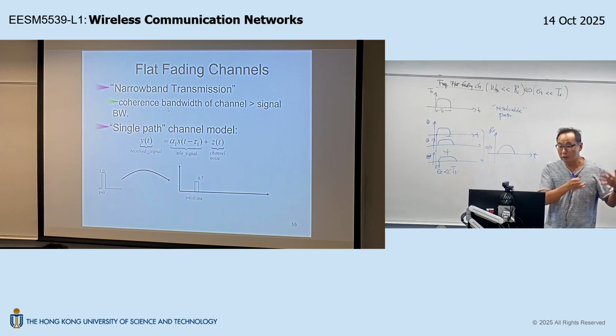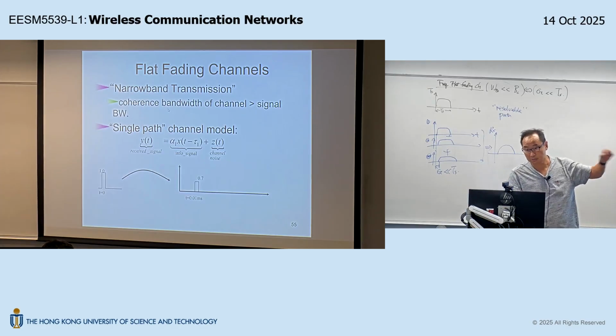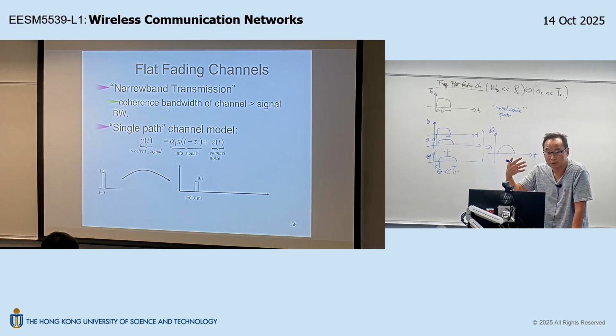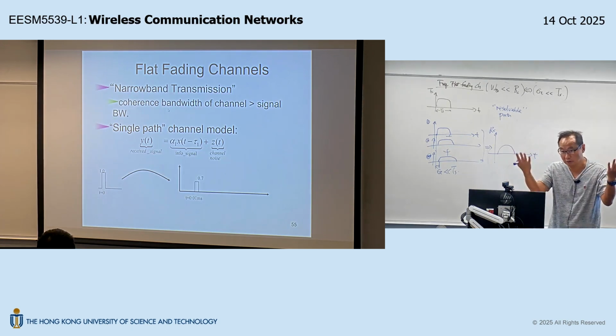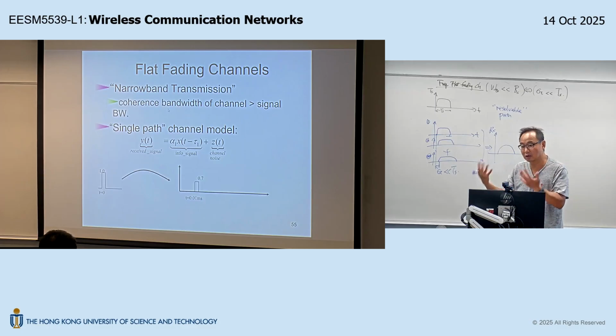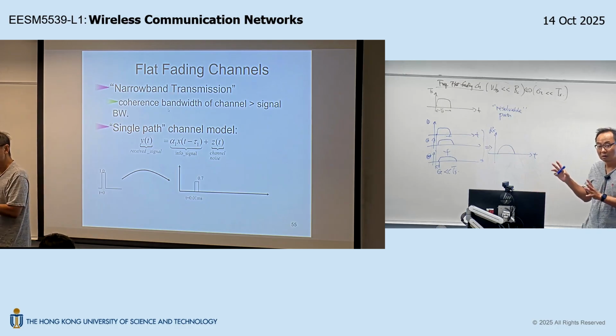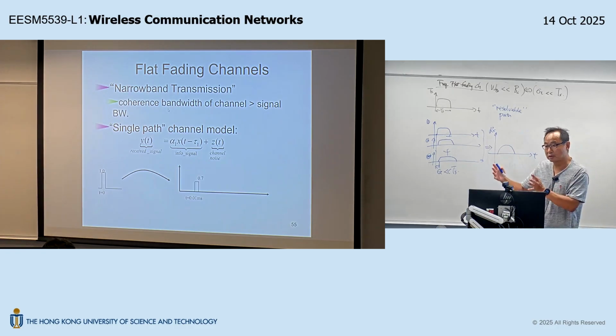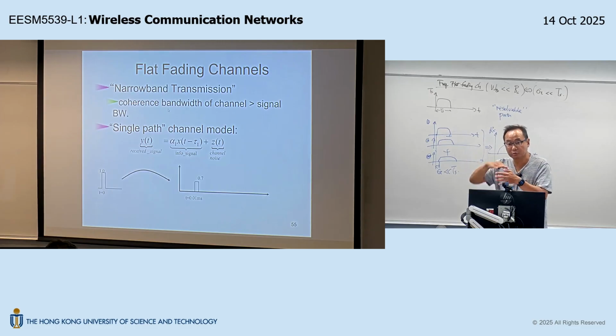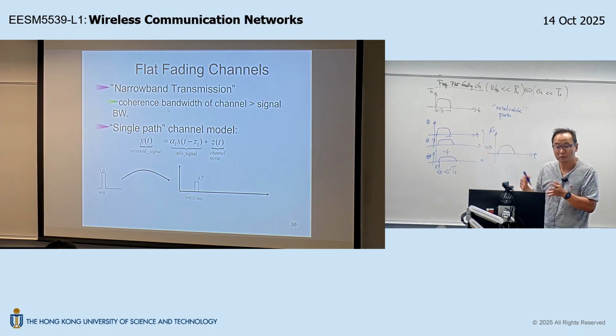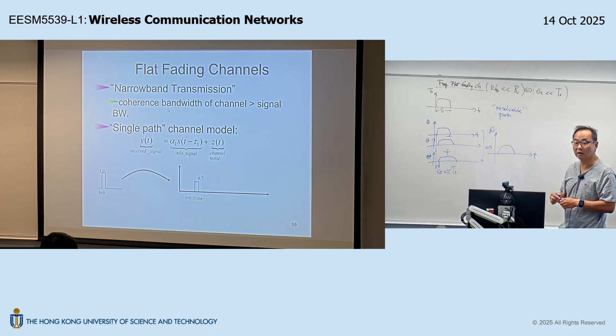So the acoustic delay spread in the staircase is pretty small. When you say one symbol, A, you will still hear your echo as one symbol, right? You hear your voice as A, but your received voice will be slightly distorted, right? So that corresponds to a single resolvable path.